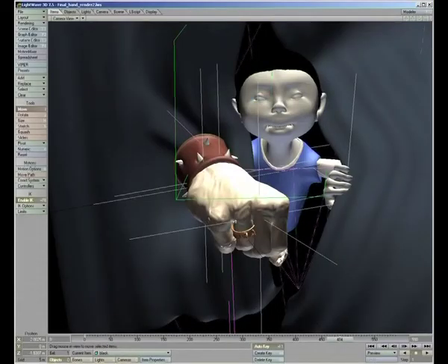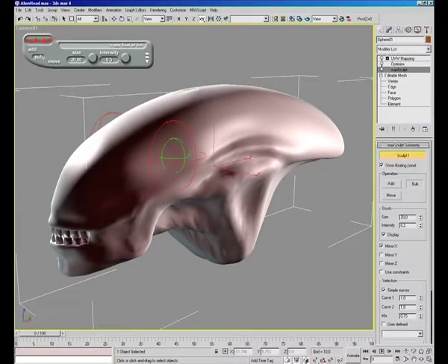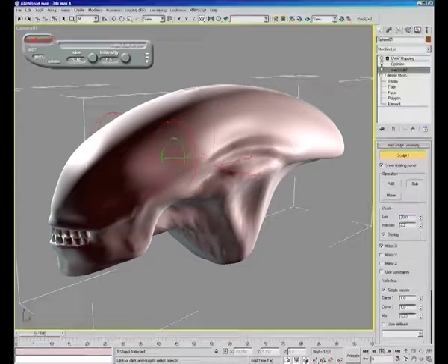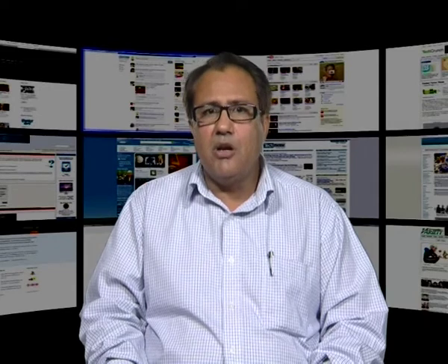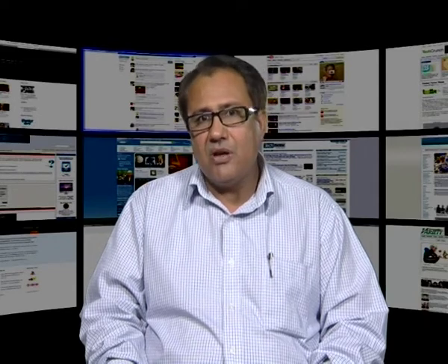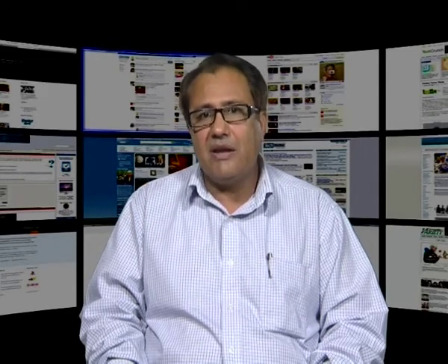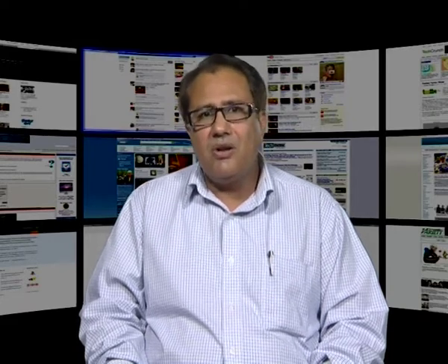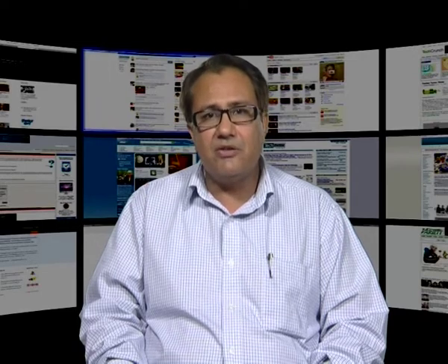When you extrude a plane surface, its shape extends some distance either perpendicular to the shape's outline or along a defined path. When you lathe a shape, a profile of the shape is rotated around a defined axis to create the 3D object. To model a scene, you place all of your objects in 3D space.